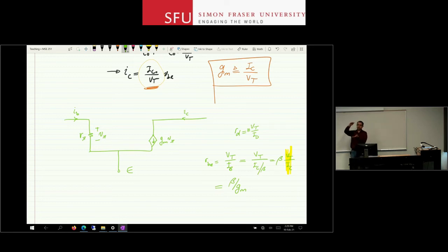Your power supply voltage is, let's say, plus and minus 1.5 volts. Those are given. They are not changing. Or plus 10 volts. And then you bias the transistor with a 1 milliamp current. And that's done. Once you choose your resistors and then establish the current, that's it. For the small signal parameters, that actually is not the case. That V in is coming from a signal source. So you really don't know what the amplitude of that signal is. You just know it is small.